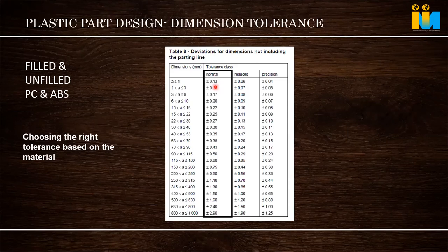So whenever, I recommend product designers give nominal tolerance wherever possible. If it really calls for it, sometimes we may give a precision tolerance, and when the parts come out, we may not be able to achieve that, but we assemble it and see the performance. The process may not be capable of meeting precision, and it is coming in the normal tolerance, and we are doing an operation trial or testing or performance evaluation, and it is working quite okay, then the normal tolerance is sufficient. We have to change the product design, document it, and change it to normal tolerance.